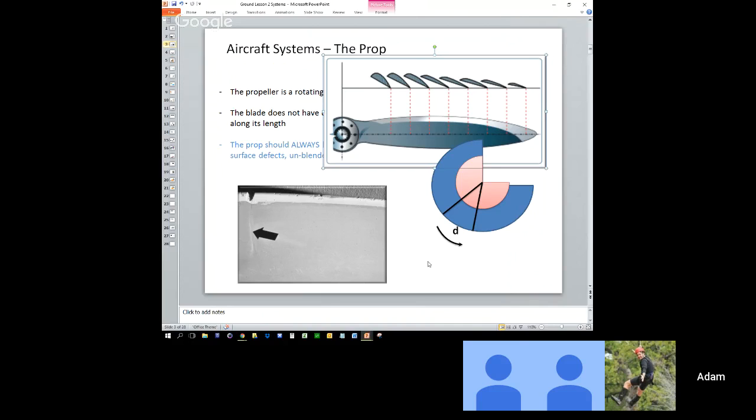Lift? No. There you go. Speed. Airspeed, right? If you pull, and I'm kind of reaching to the last chapter. So Chris, if this is something we haven't gone over yet, but as you increase the angle of attack and you climb, airspeed is going to slow down, right? So to generate the same amount of lift, you've got to increase the angle of attack for slower airspeed.